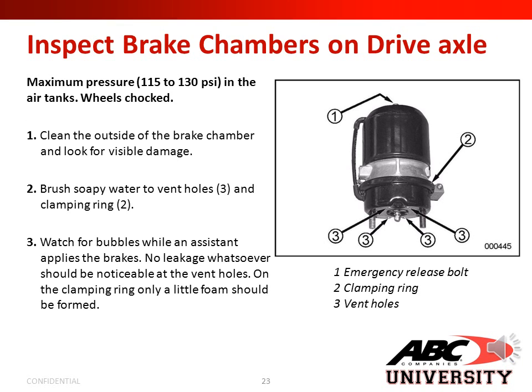Inspecting your brake chambers on the drive axle. Make sure you have a maximum pressure of 115 to 130 psi in the air tanks. Wheels are chocked. Step 1. Clean the outside of the brake chamber and look for the visible damage. Step 2. Brush soapy water to vent hole number 3 and clamping ring number 2, as shown in the picture to the right. Watch for bubbles while an assistant applies the brakes.